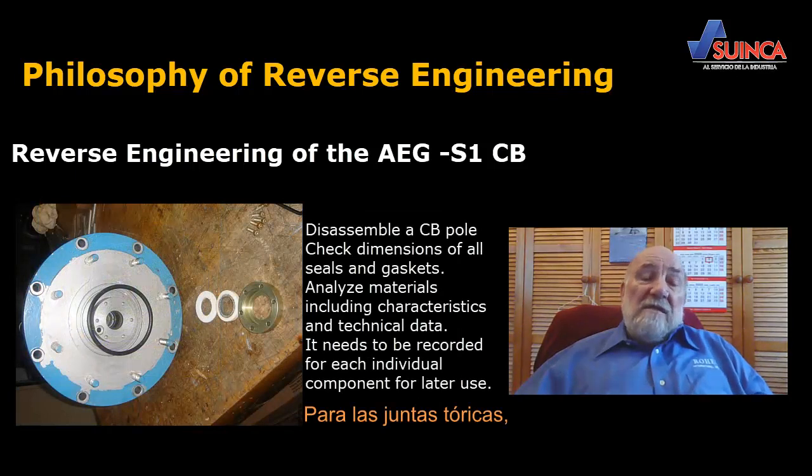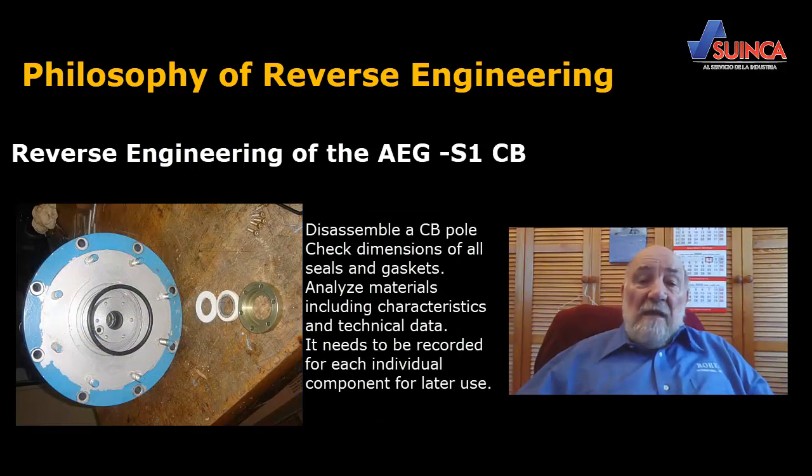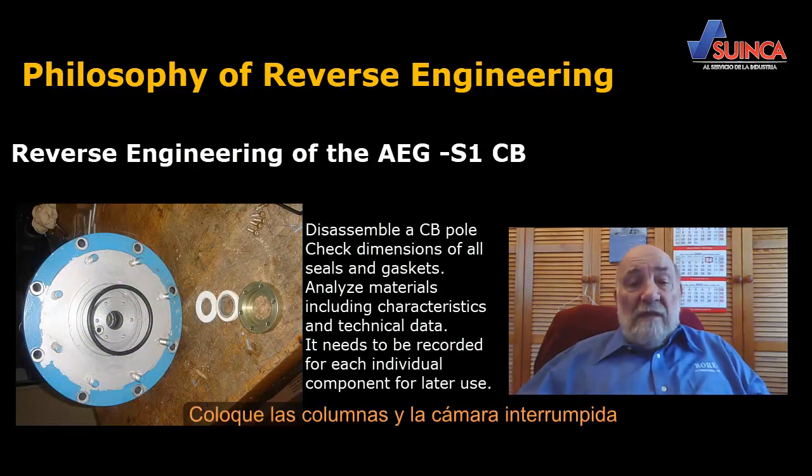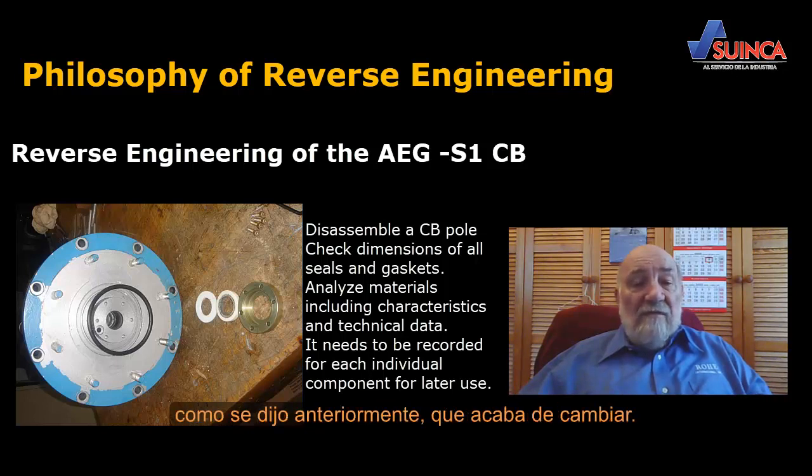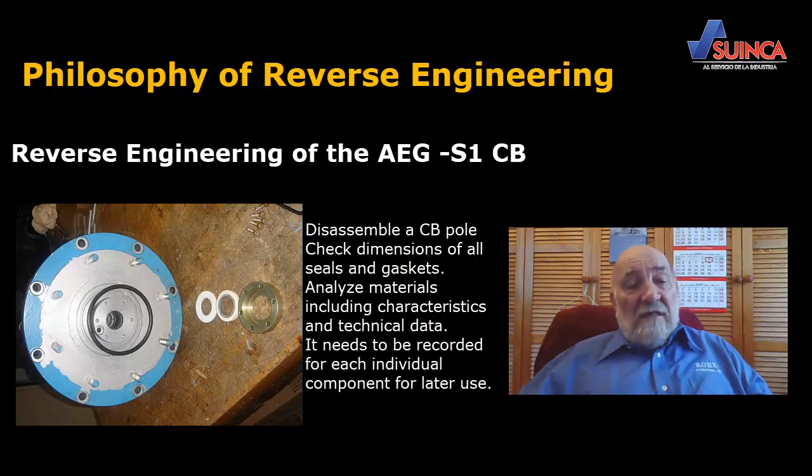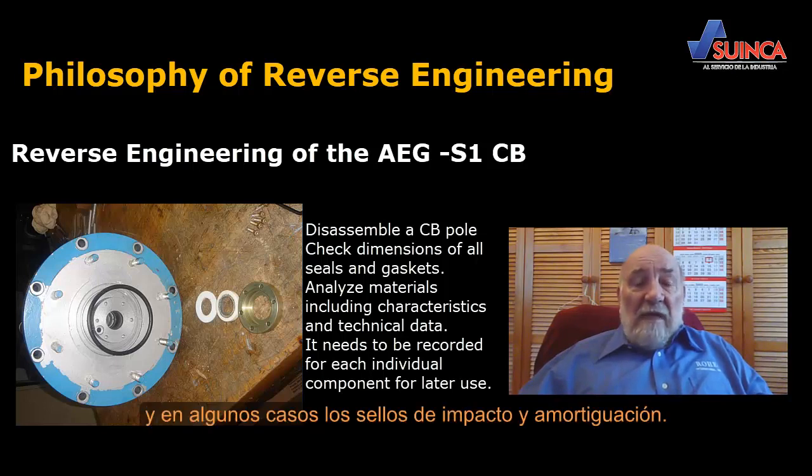For the O-rings of the pole, the columns and the interrupter chamber, as said previously, we just changed the O-rings and in some cases the impact and dampening seals.